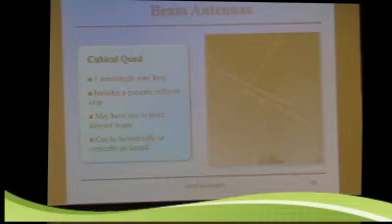Generally speaking, and this is in some of the antenna books, a 2-element quad is considered to have about the same gain as a 3-element beam. But you still don't see that many quads because they're 3-dimensional, they're just a little hard to keep up. Again, they tend to be more susceptible to ice damage, etc. But for people that have them, they generally love them and they do a great job as long as you can keep them in the air.